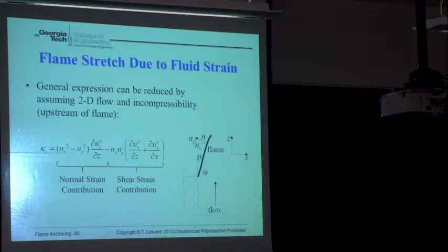Is the flow in bulk accelerating or decelerating at the flame? Well, what would cause a flow to accelerate or decelerate? Usually flames are stabilized at points of rapid expansion. So it would be very typical for the flow to be bulk decelerating as it's entering a combustion system, right? I don't care what your geometry is.